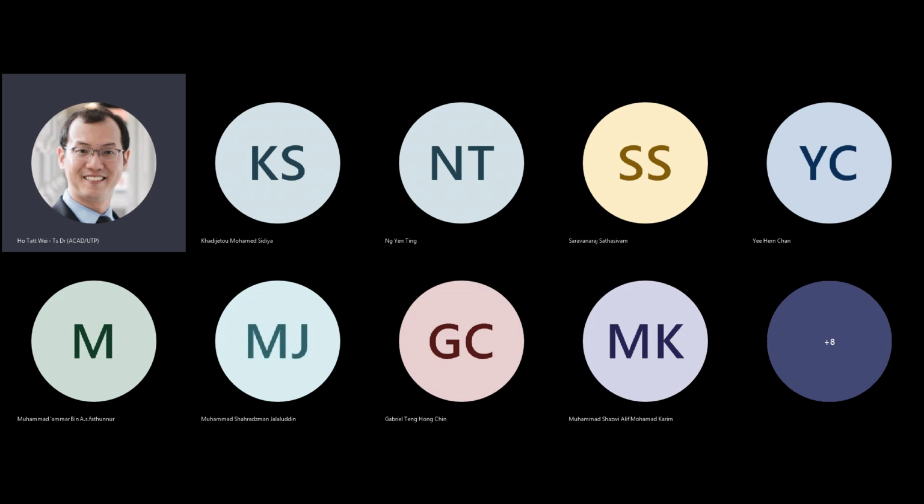So there will be a particular logic pathway, maybe the evaluation of this path here, going through 1 gate, 2 gate, 3 gate, 4 gate, 5 gate, right? So this path here is going to be longer. It takes more time, right? Because the computation has to pass through this set of transistors first, then this set of transistors, then this one, as opposed to this path. This path is just very quick, right? It just goes through one gate, right? So this is actually the critical path in this complex logic sequence, right?